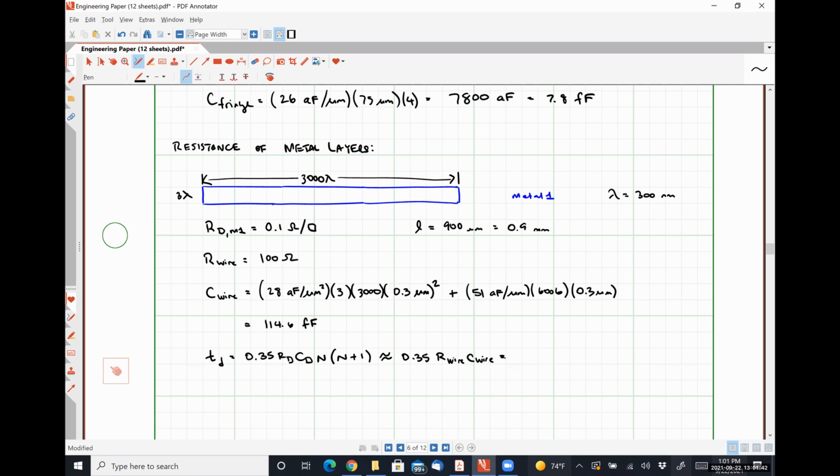so you had like the times 10 to the 18 for your attofarads and times 10 to the -6 and all that kind of stuff. And so I set the problem up in such a way, I tried to anyway, that by expressing lambda in terms of microns, we were going to get an answer. So these micron squared cancels out this per micron squared, this per micron cancels out this micron and all that kind of stuff. So that you would just get an answer that you would know to be in attofarads, divide it by 1,000 and you get it in femtofarads, which is exactly what this number gets. Now, how I screwed it up in my notes, God only knows.